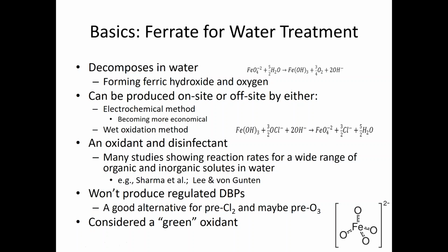Now, ferrate has been proposed for a long time as a great oxidant and more recently as an effective disinfectant. There's a lot of work that's been done over the years, especially on ferrate's ability to oxidize contaminants and remove contaminants in water and wastewater. One of the great things about it is it won't produce regulated DBPs, at least very, very little in the way of regulated DBPs. So it's a great alternative if you need some pre-oxidant and you're using chlorine. It's a great alternative to chlorine, and it also is a pretty interesting, low-cost alternative to ozone, we think. And it's considered a green oxidant.